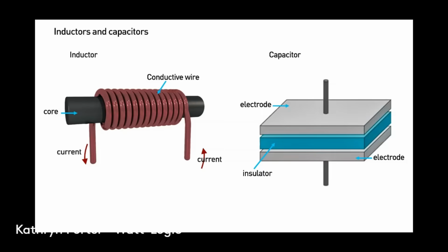One way to visualize the action of an inductor is to imagine a narrow channel with water flowing through it and a heavy water wheel that has paddles dipping in the channel at the end of the channel. And imagine that there isn't water flowing to begin with. So then you get the water going, and the paddle wheel will actually try and prevent the water from flowing until it's come up to speed with the water. And then if you try and stop the flow of water in the channel, the spinning wheel will actually try and keep the water moving until the speed of rotation slows back down again to the speed of the water. And that's effectively what the inductor does with the flow of electrons in a wire. It resists change in the flow of electrons, and therefore the flow of current.